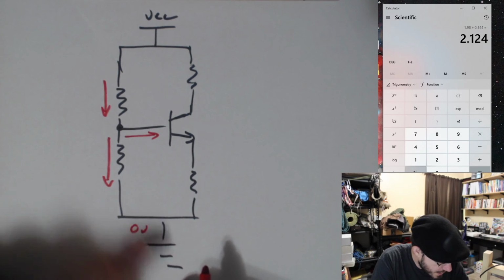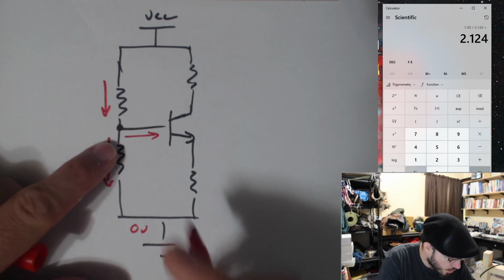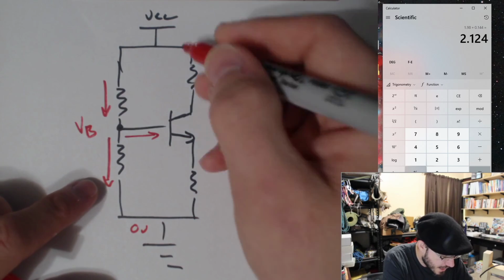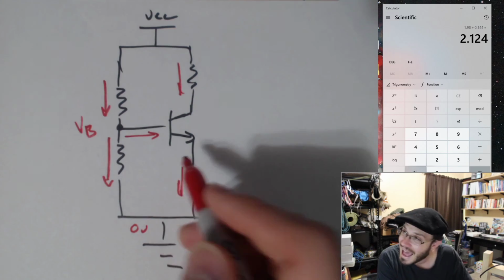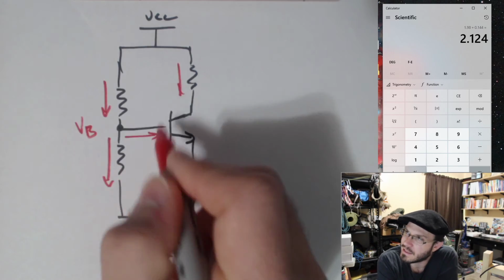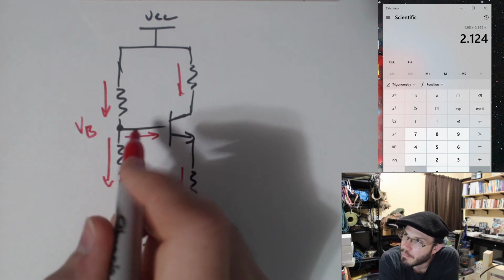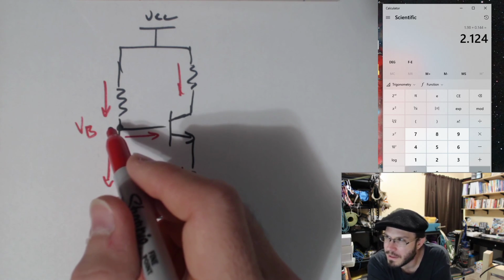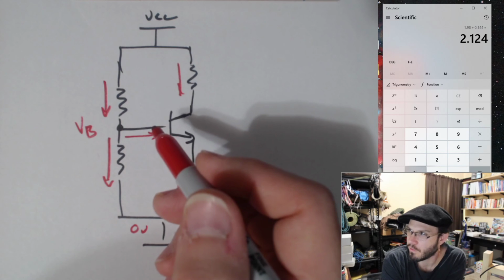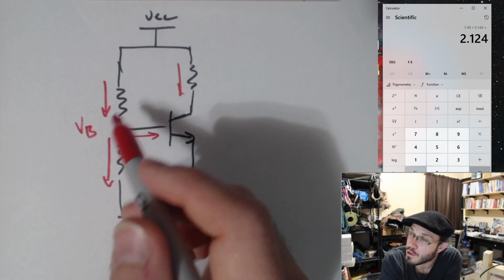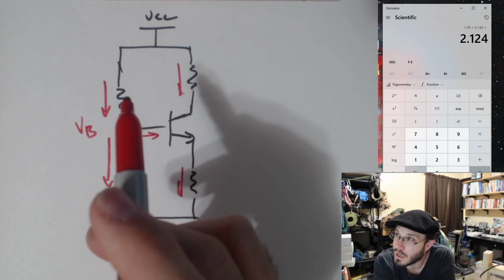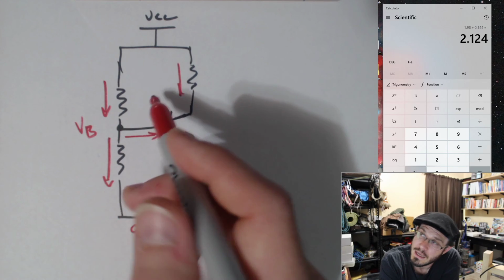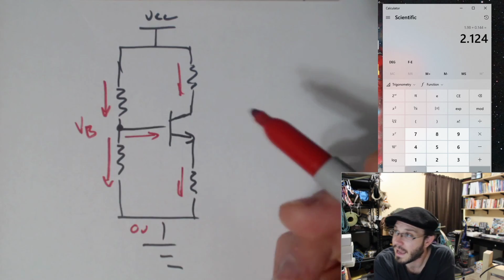I have a reference node here. I have a voltage applied here. I can write out what this voltage is in terms of these currents, and I can do this all throughout the circuit. As it turns out, applying nodal analysis to this portion, but just this portion, ends up making this problem that really couldn't be solved any other way all of a sudden solvable. Now, as it also turns out, you can form a really good approximation for this circuit using a Thevenizing technique. So you could Thevenize this front half and simplify it to something else.